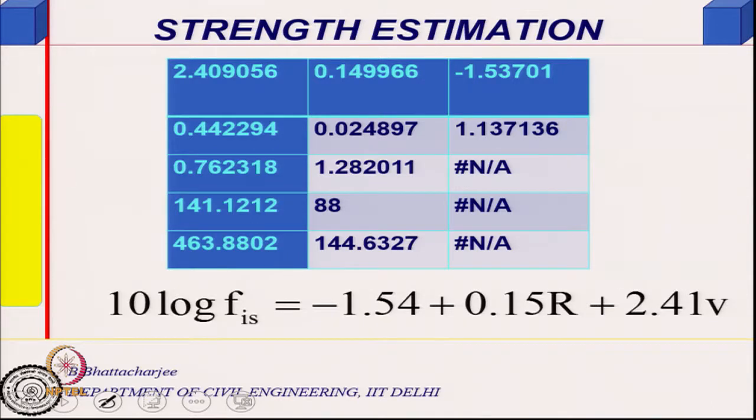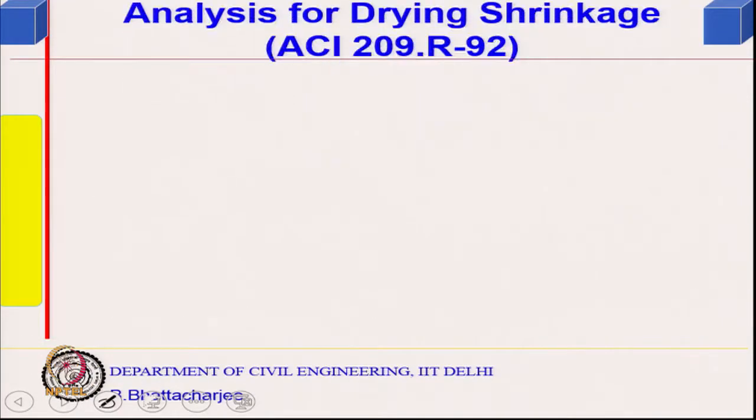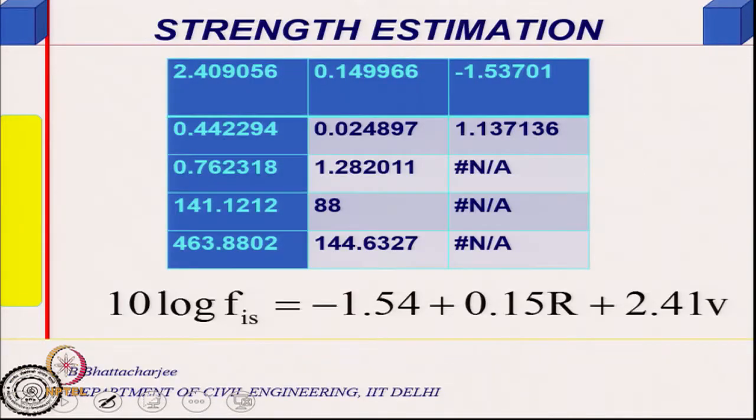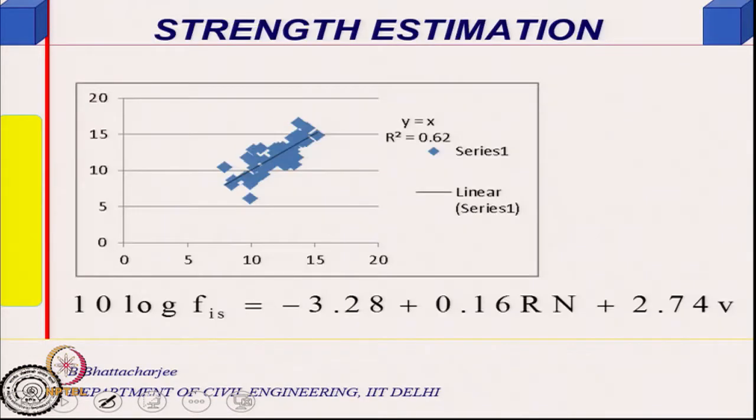We used this data, then we said you do more tests. A few more tests were done, a few more cores were taken, and we did improve the situation even better. So we got somewhat better. This is the kind of scenario where you can improve it by doing more core tests and results, to establish a better correlation.